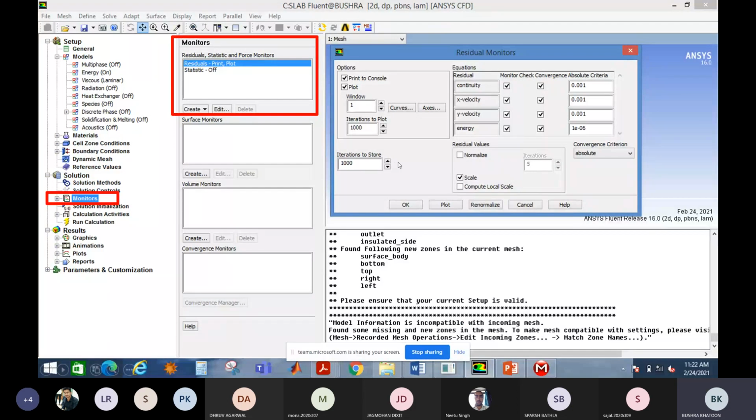This is important for solving your energy equation, that is residuals. Basically residuals give the limit up to, means suppose we are using a numerical method to solve the energy equation, ठीक। And we have a temperature, left wall side temperature is 373 Kelvin, but once this CFD tries to solve this equation, there is always some kind of error.